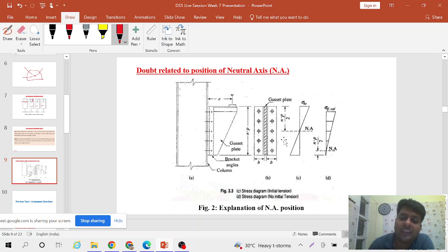What they are actually trying to say is that in the case of HSFG bolts, initial tension is induced in the bolt. Do you remember? In the HSFG bolt, by giving proper clamping, means tightening the nut, we develop initial tension in the bolt. We have discussed pre-tensioning during the discussion on HSFG bolts. So in pre-tensioned bolts, the clamping force is very high in those connections.